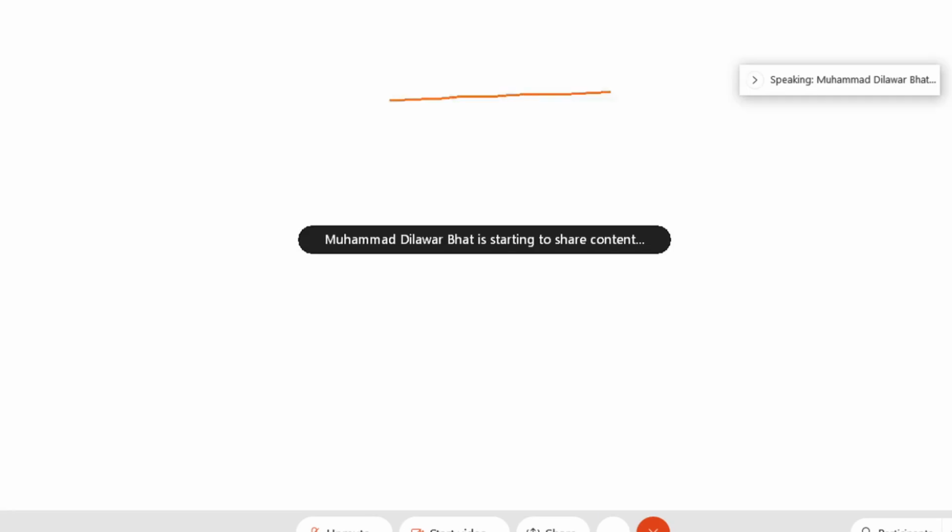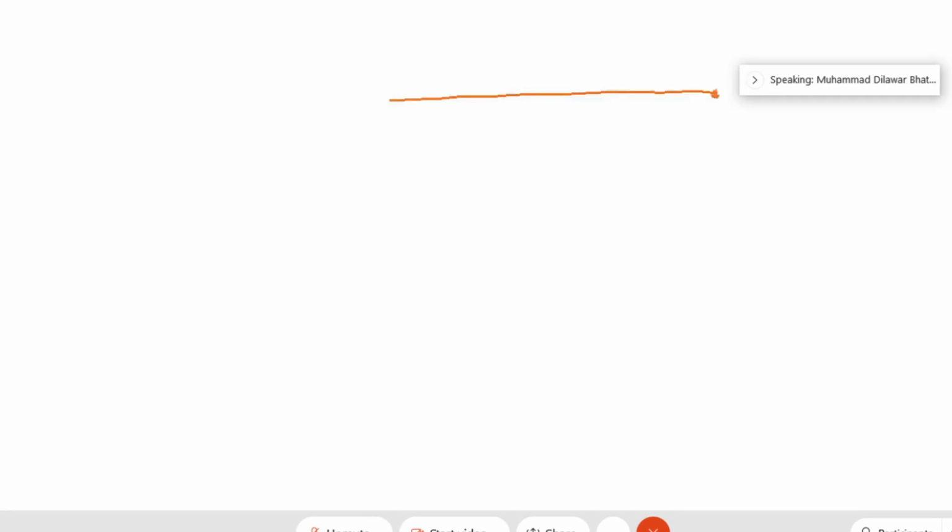At point E it is 0, and at one more point we have a load of how much? 700, and then the distance was 1.5. 700 into 1.5, here you have a moment of how much? 700 into 1.5 is 1050, right?